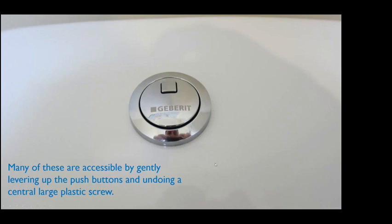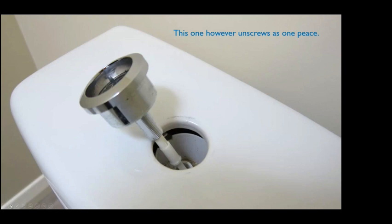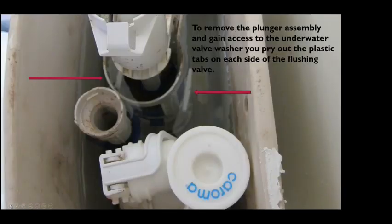So yeah, a whole range of different things for them. Some you just lift the lid off, other ones you've got to pop the cap up, unscrew it, etc. to get in there. Like this funny one. When you initially set it up, obviously you want to set the overflow level probably an inch at least below the internal overflow. Most everything's got an internal overflow now. Real old-fashioned ones like the old duco center flush system would have had an external overflow, but even some of those may be converted to an internal one.